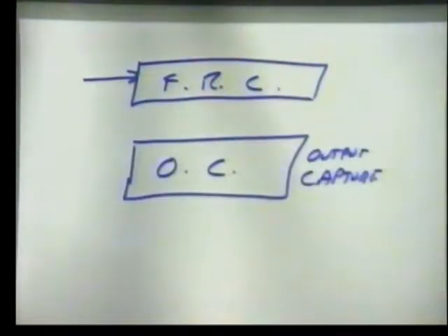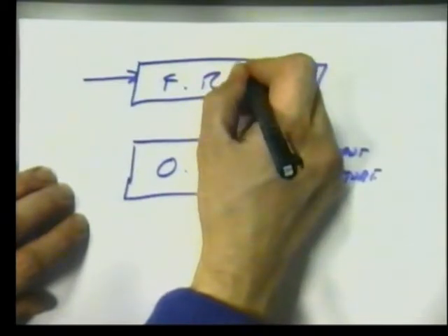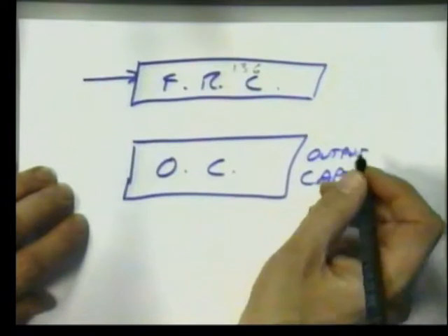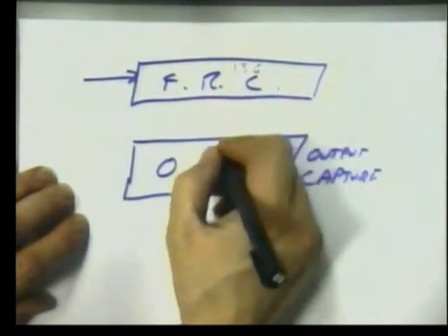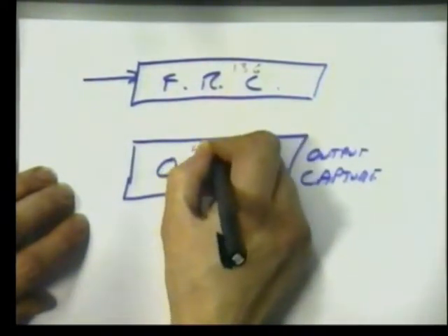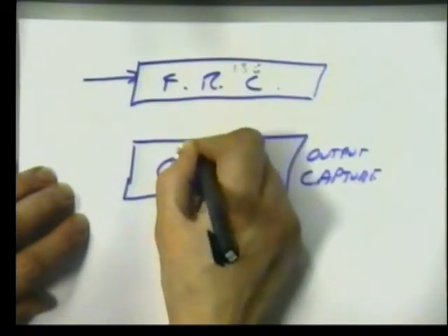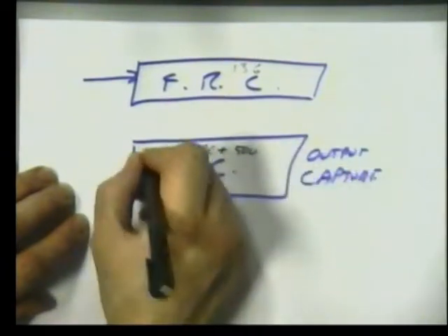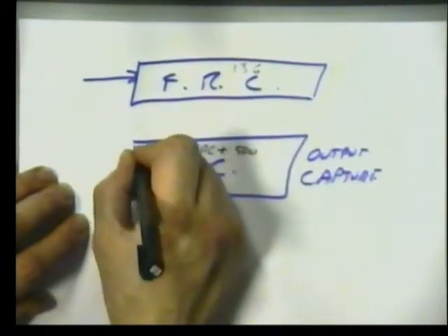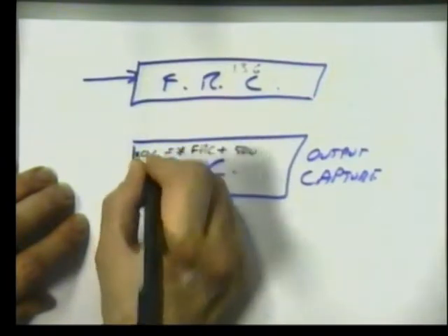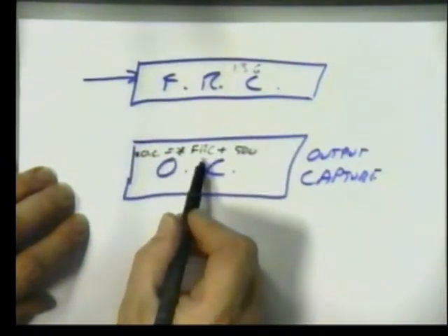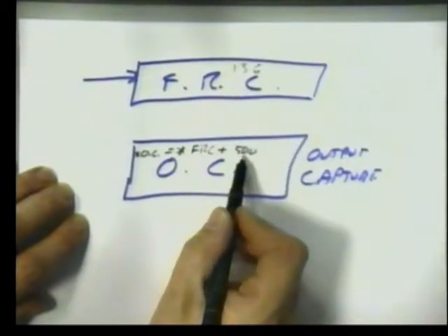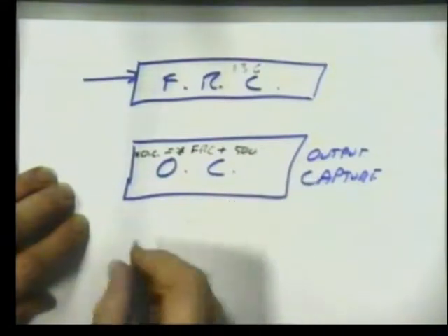That then times out. Why does it time out? Because let's assume the number in here was, say, 136 and we wanted to have an interrupt, say, 500 counts later, so we write into here using C: *FRC plus 500. So there is our code, *output capture, a pointer to the output capture, is set to a pointer to the free running counter, the current contents of the free running counter, plus 500. Very simple bit of code.